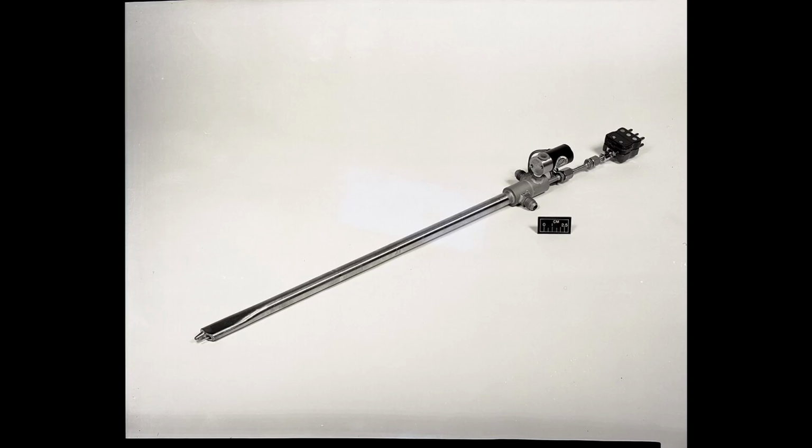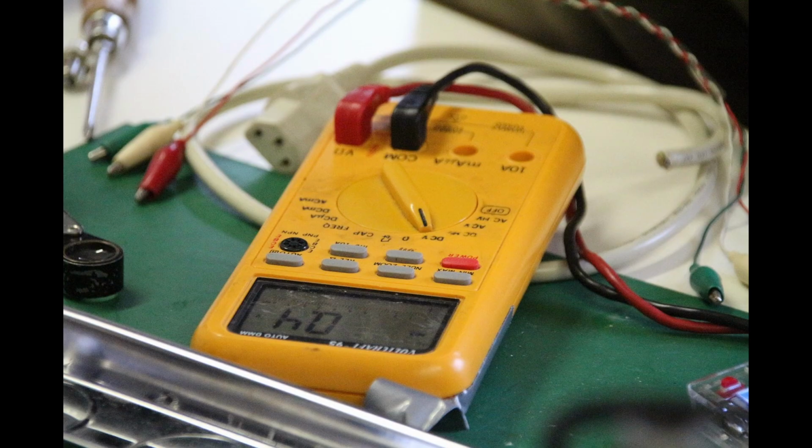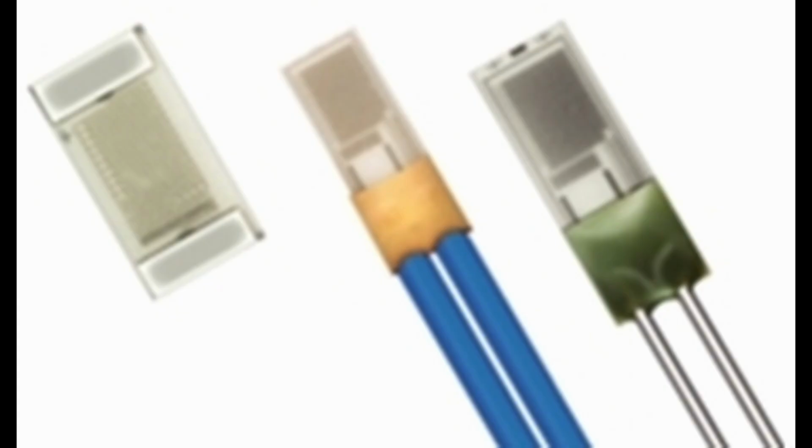Temperature measurements can be made using a thermocouple. This is created when two metal conductors are joined at a junction. When the junction is exposed to a temperature, a voltage develops across the conductor ends. This can be measured with a circuit. For example, a thermocouple made from nickel chromium and nickel aluminum alloys, when exposed to 300 degrees Celsius, produces a 12.2 millivolt output.